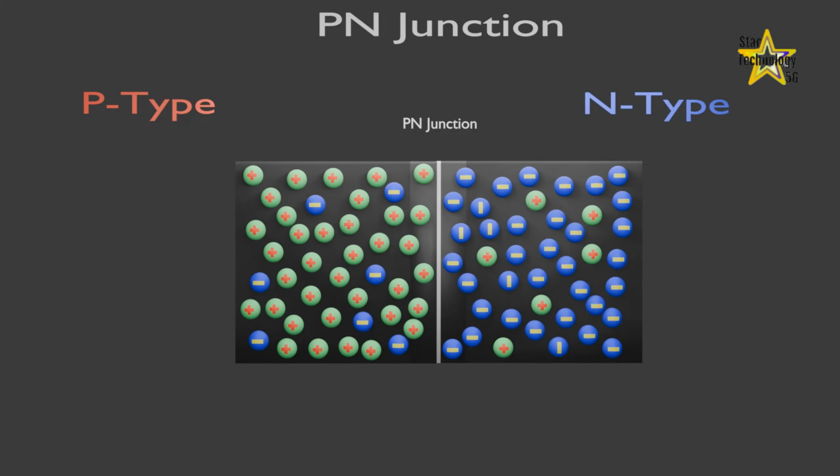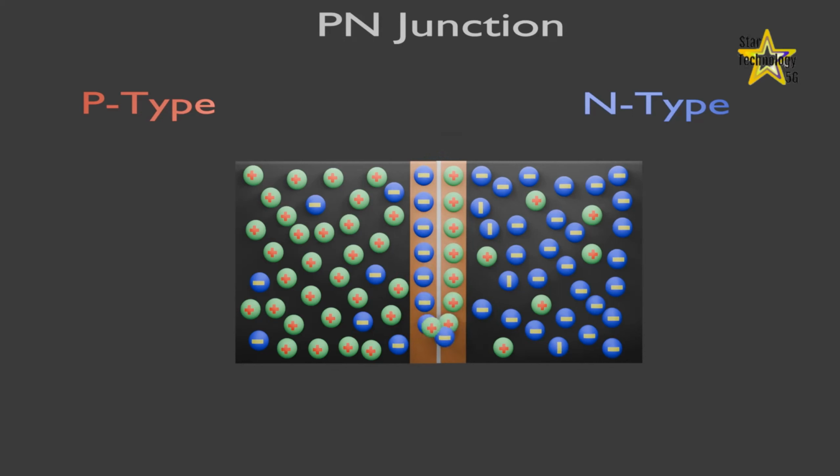When the p-n junction is formed, n-type electrons begin to flow into the p-type semiconductor. That is, as the atoms lose charges, areas with non-mobile charges are produced. This event continues until a charge balancing occurs. The flows of these majority carriers in the semiconductor will affect the region around the junction. A positive charge migrates to the n-type side of this region, and a negative charge migrates to the p-type side.